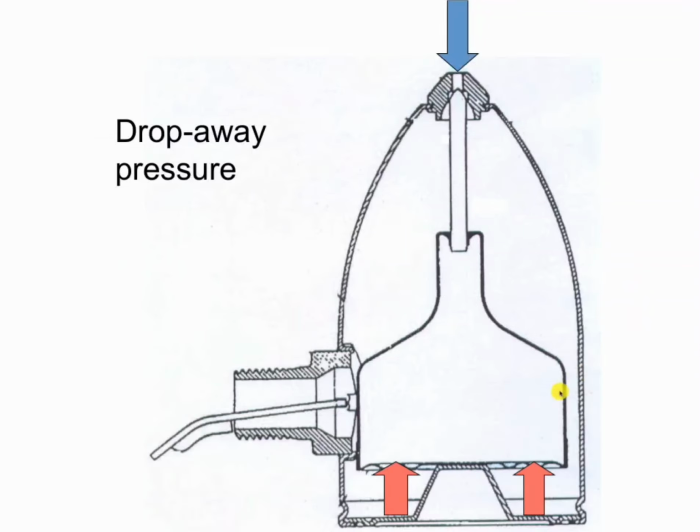And what I want to do is just take note of the two pressures that he referenced. He referenced 2 to 5 psi. Now, just based off of my experiences and what I've seen, 2 to 3 psi is what you would typically find in a small residential cast iron boiler. Maybe a 3-section, maybe no more than 7 sections. They typically set these at about 2.5, 3 psi.